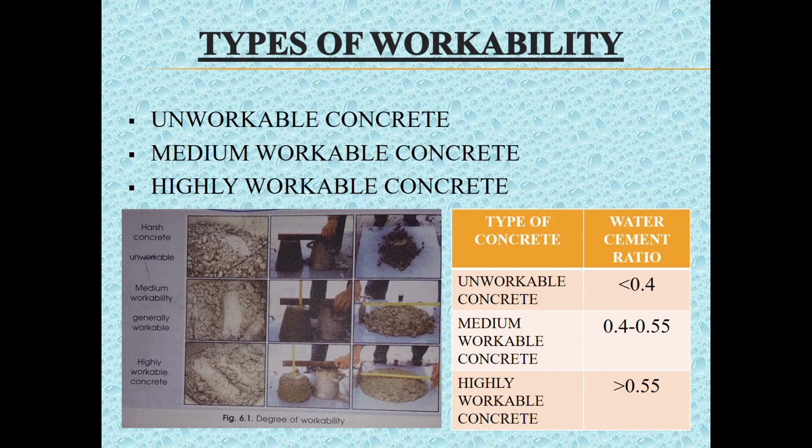There are various types of workable concrete, such as unworkable concrete, medium workable concrete, and highly workable concrete. Unworkable concrete can also be called harsh concrete. It is a concrete with very little amount of water and is difficult with hand mixing.